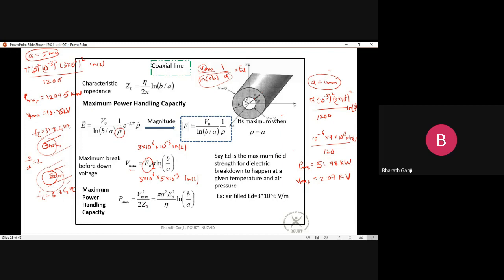So I can see that compared to a 1 mm cable, a 5 mm cable, the broader or bigger one, actually has a very good power handling capability. It can deal with very high power or very high voltage compared to a thin wire. But the problem is for a is equal to 5 mm, the cutoff frequency is very small. So higher order modes come in very quickly.